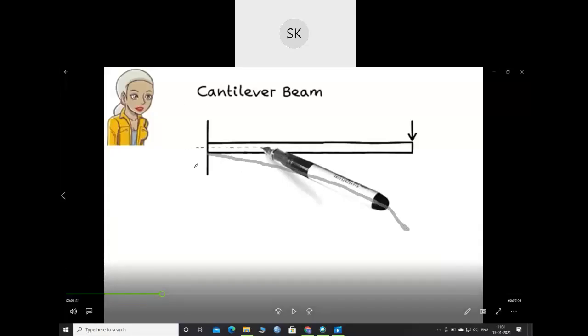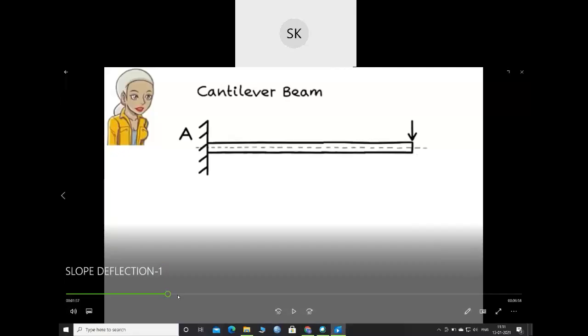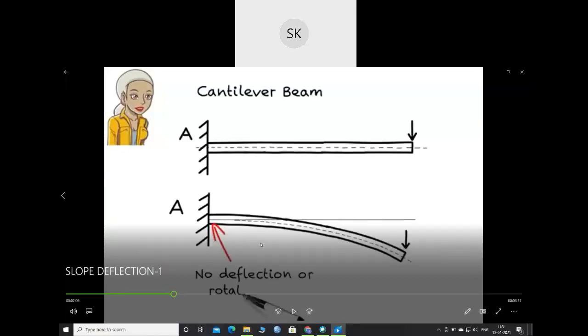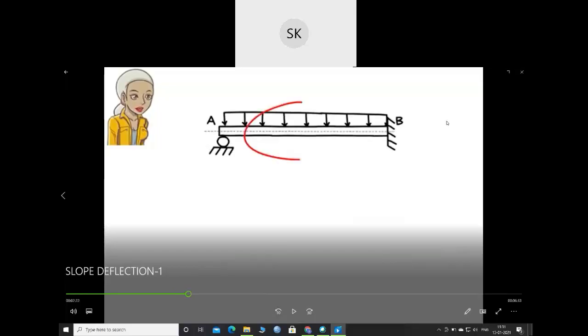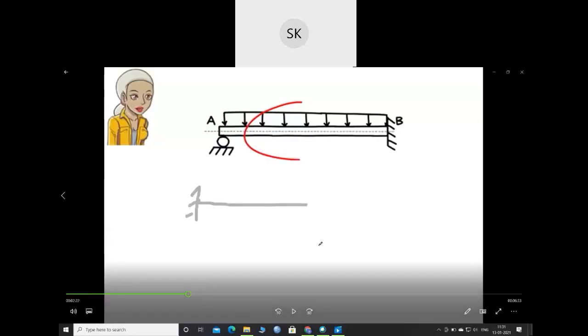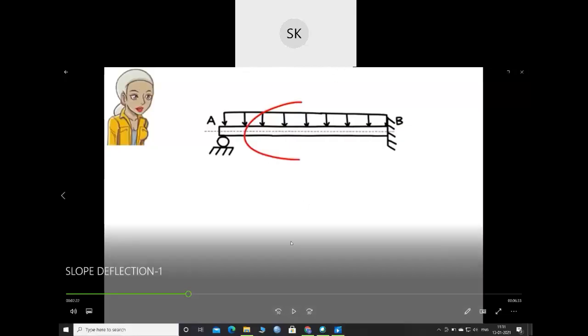The value of the total load is indeed the magnitude of the equivalent concentrated load. But where on the beam would we place the concentrated load? The location of the concentrated load is the geometric center of the area formed by the distributed load. In this case, we know that the center of the rectangular load is located at the midpoint of the beam. Now we're ready to calculate the beam's support reactions by formulating the equilibrium equations and solving them for the unknowns.